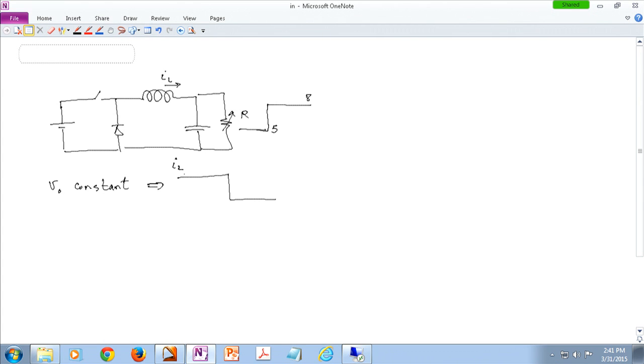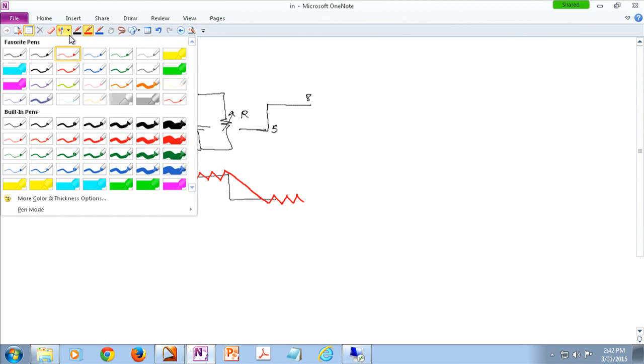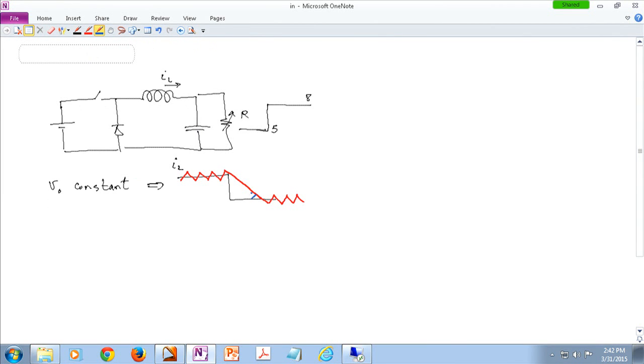So ideally, this is your inductor current, but practically, your inductor current has some ripple on it. All right, something like this. So let's say as soon as the load changes, you realize the load has changed and just keep the switch off, meaning don't send energy to the output, let the output capacitor discharge by itself. But even though you are keeping the switch off, still your inductor current is not following its reference in this area.